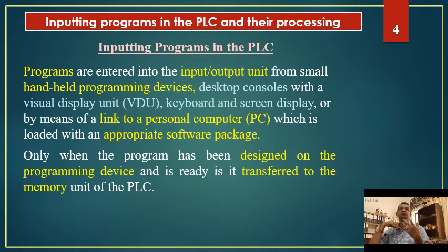Whenever we have to have a program for a PLC, first of all, it needs to be written somewhere. Normally, like in Arduino, an IDE, Integrated Development Environment, is used, which acts like a compiling station for writing a program. In the IDE, we can write a program, compile it, troubleshoot it for errors, and compile that particular program. Once it is compiled, then that program can be transferred from a personal computer to a PLC.